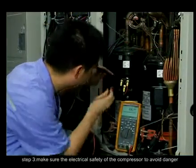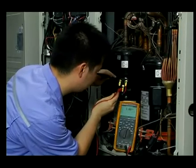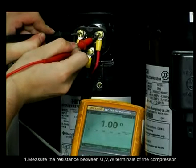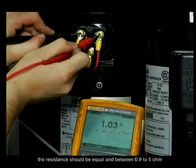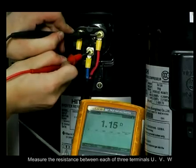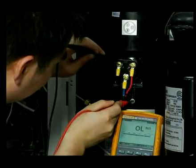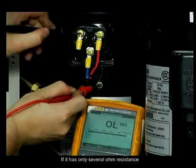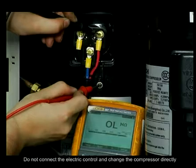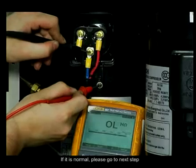Step 3. Make sure of the electric safety of the compressor to avoid danger. 1. Measure the resistance between the U, V, W terminals of the compressor. The resistance should be between 0.9 and 5 ohm. Measure the resistance between each of the 3 terminals, U, V, W, and the ground to make sure it is in the mega ohm range. If it has only several ohms of resistance, that means the compressor has been short-circuited and damaged. Do not connect the electrical control and change the compressor directly. If it is normal, please go to the next step.